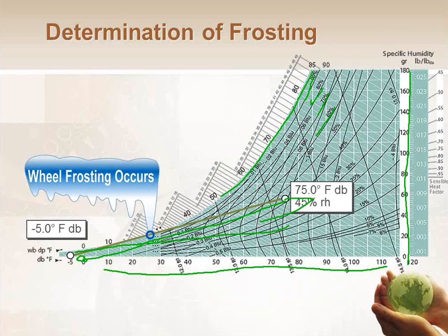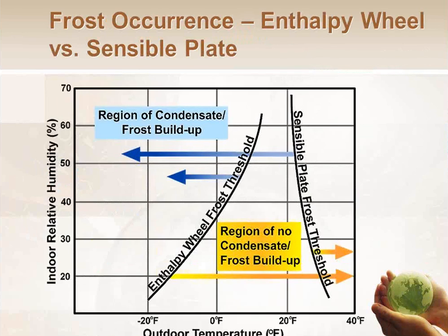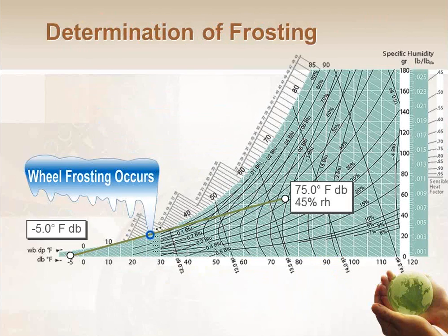Here, let's see if we can clear that a little bit. So if I heat that to 80 degrees, the line moves over to here. There's my new dot. Now if I draw the line, it's not very straight here, but you can get the idea. It's hard to do with the mouse. I will be able to avoid hitting that saturation curve. So it's easier to heat the return air than it is to heat the outside air coming in, although it will be counterintuitive in your thinking.